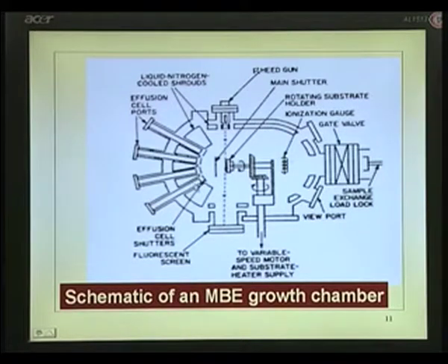If you want undoped gallium arsenide, keep the gallium and arsenic shutters open. If you want aluminum or indium, you open the shutter which contains it. The relative composition is controlled by the temperature, the flux. So, it becomes more involved here. Now, you can see this is the side which is giving those impurities, dopants or the constituents, and this is the substrate holder.